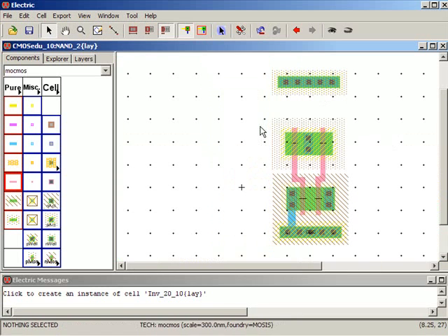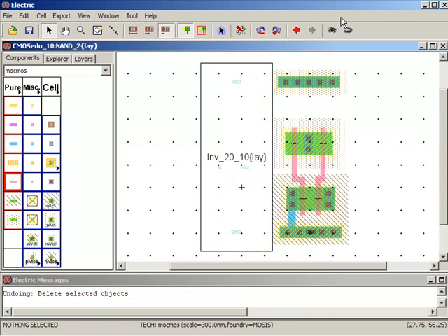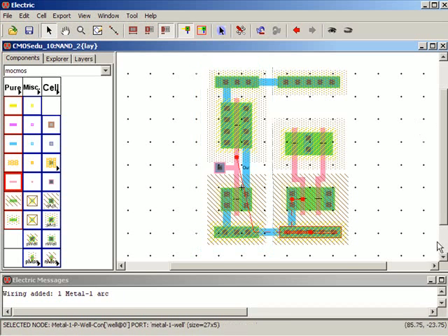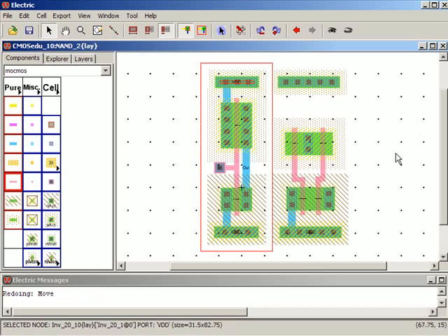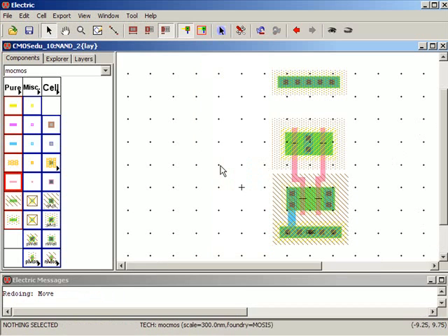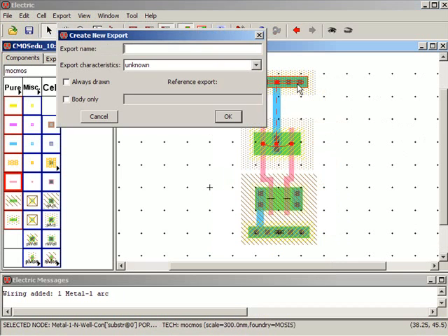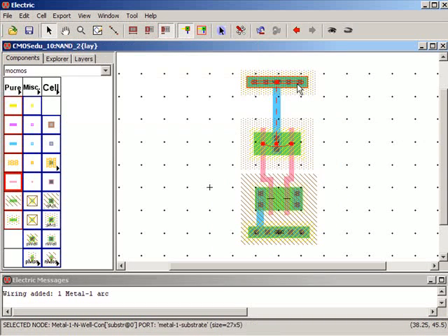Okay, delete this, we're lined up. Whoops, Control Z, let's make sure I'm lined up before I actually do delete that. Looking good. So I can left click and drag, and that looks good. Left click and drag, and that looks good. Control Z a couple times. Whoops. Control Y for redo, and then delete this. Fit, and now we can go up here and connect that node up. Export this, Control E, VDD. So now I can export these.